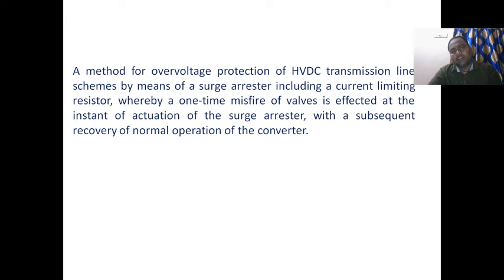So a method for overvoltage protection of HVDC transmission line schemes by means of surge arresters, including current limiting resistors, whereby a one-time misfire of valves is effected at the instant of actuation of the surge arrester, with a subsequent recovery of normal operation of the converter.